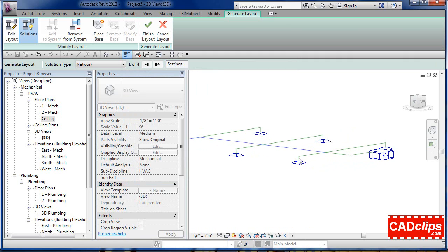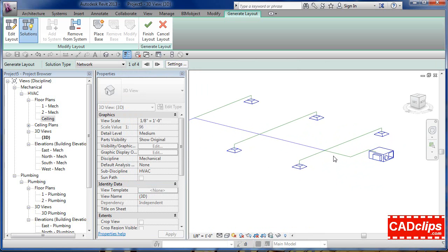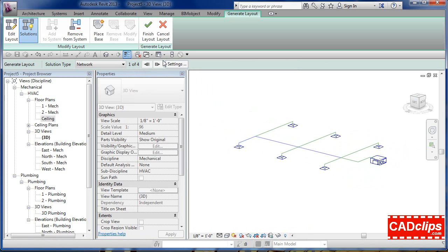Right? It's going to do the little flex duct at the ends, but the main thing is that it's at the right level. Now we can go in here and say, okay, there's one of 4 options. So they're offering us this routing option, this routing option. So it's giving us some options here. That one looks good to me.